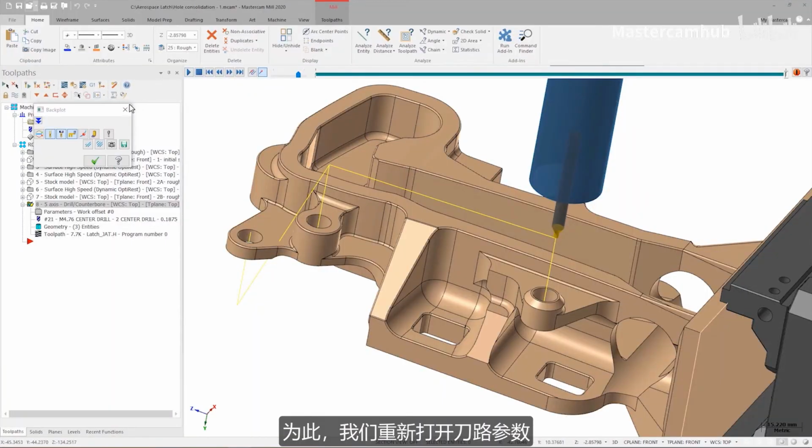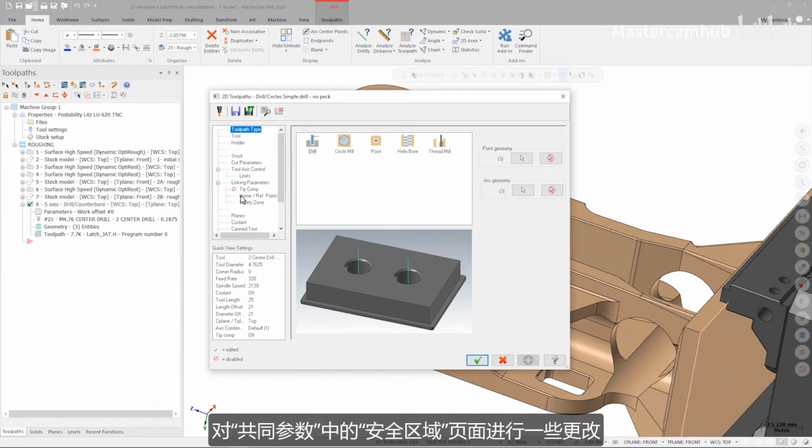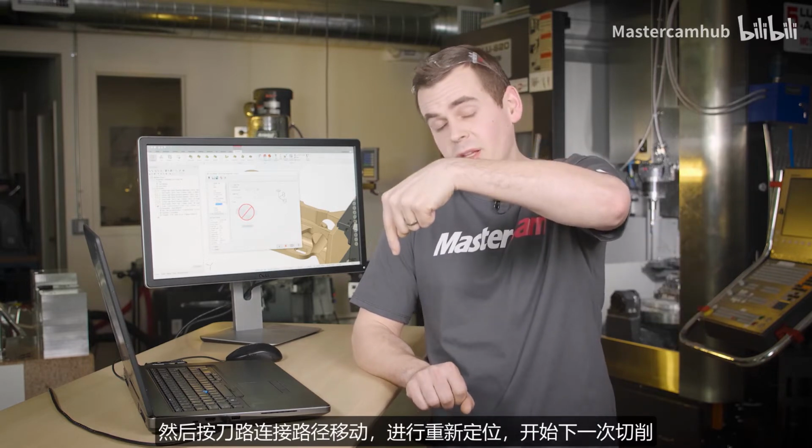To do this, I need to reopen the toolpath parameters, and under linking parameters, I need to make some changes to the safety zone page. If you're new to multi-axis programming, a safety zone is an area you can specify where Mastercam will not perform any linking moves. Instead, the tool will retract out past the edge of the safety zone, and only then will the linking move reposition the tool for the next cut.